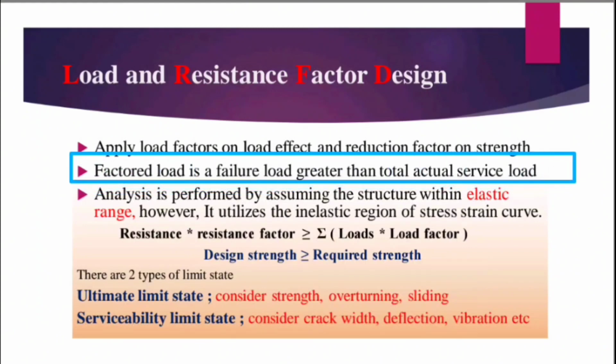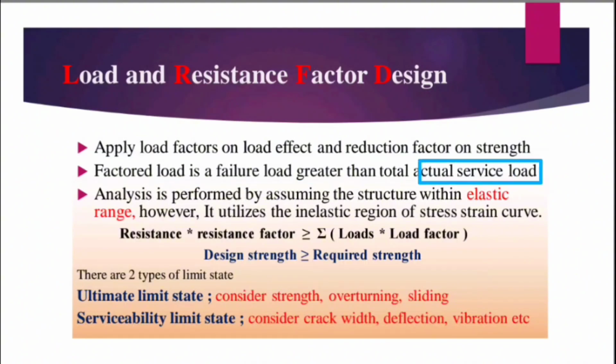Factored load. What is factored load? In actuality, the loads that act on a structure are called the working load. We will amplify the working load by a factor called the load factor, which is also always greater than unity, that is, 1. So remember this. So what is actual load? Actual service load. Service load is a load which might be experienced on a structure.